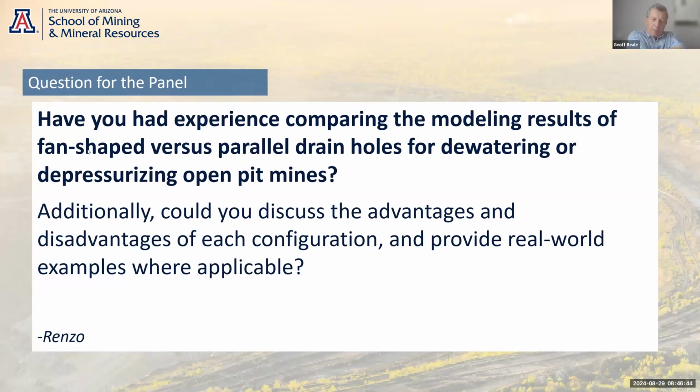Okay, I'll give it a crack, and I'm going to answer the second bit first. So we talk about drilling horizontal drains in lines perpendicular to the slope, or in fans. The advantage of a fan is you can keep the drill in the same position and drill multiple holes.